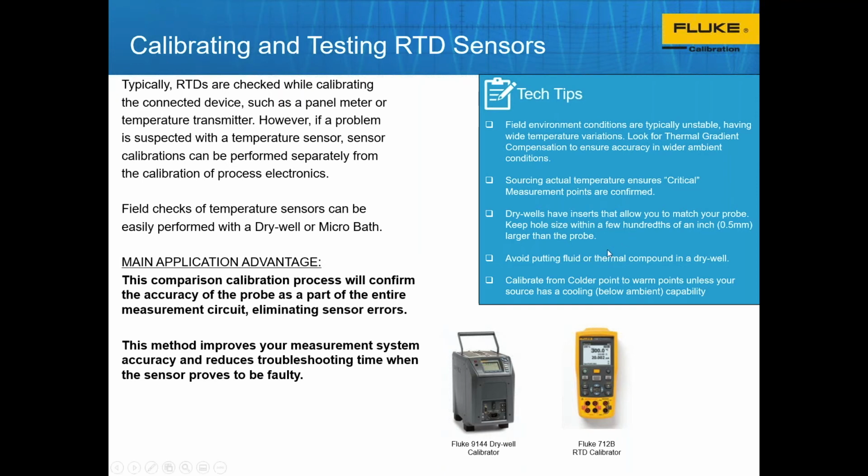We mentioned the different wells that you can use and choose from. One thing I want to point out is this fourth bullet down. If you're using a dry block or a dry well calibrator, I highly recommend that you keep it dry. We have some people that will use oil on the side of an insert in an attempt to create better thermal conduction. You don't need to do that.